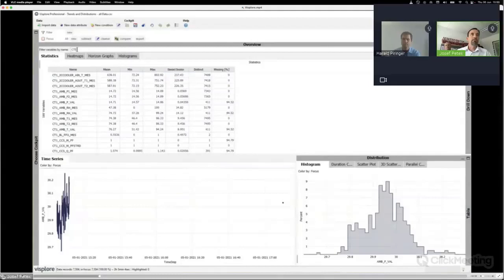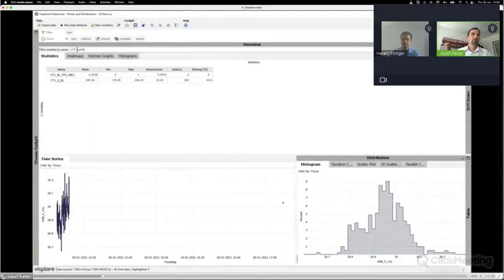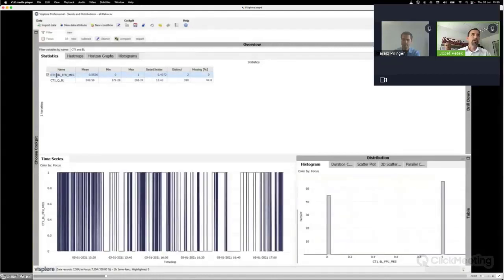The full load information of a gas turbine is something that is provided by the engine's control system through a base load indicator, and this base load indication is also part of our data set. So I'm looking for this indicator parameter. And what we do next is we want to select all data sets where this indicator parameter shows a value of 1, indicating full load.